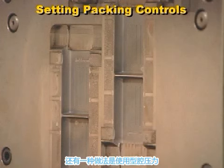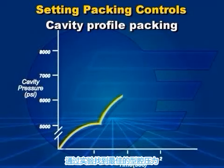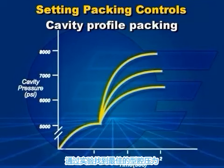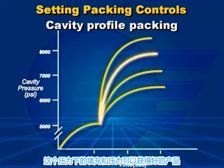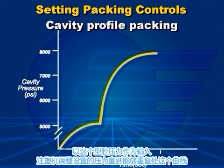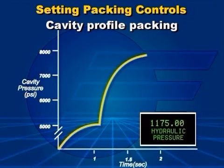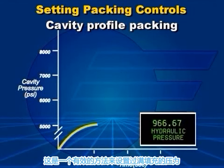Another method of cavity packing uses the cavity pressure as an input. If a cavity pressure transducer is installed in the mold, the packing rate and pressure can be more accurately controlled. Through experimentation, the ideal cavity packing pressure curve is found. This curve reflects the packing rate and pressures that produce parts with the desired properties. Using this cavity packing profile as its input, the control system adjusts packing rates and pressures as necessary to replicate the curve each cycle. This is a sophisticated and accurate means of controlling cavity packing.